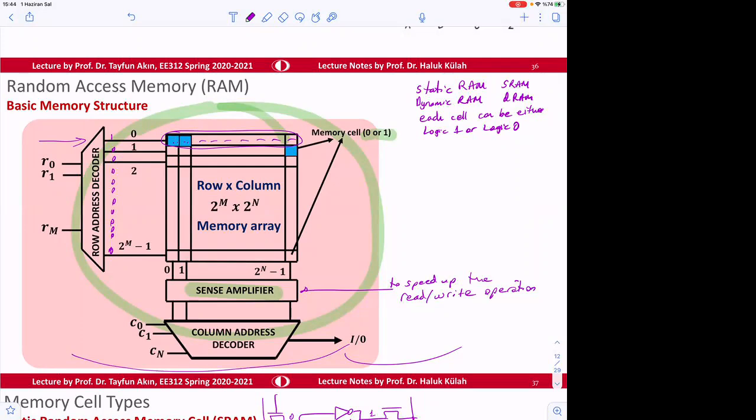If we want to make maybe 8 bits, we will be forming 8 of this same structure. But that's a design consideration. Sometimes they make it so that 2 bits are stored, or maybe more. But here in the design, at least in the configuration, we will be trying to access 1 bit. Let's say in here, we will be accessing. And how do we access that? We select one of them, 1. And then we also select, let's say this one is 1, so that we can read this data to the output.